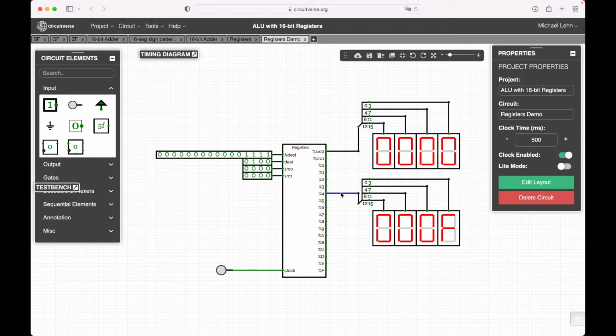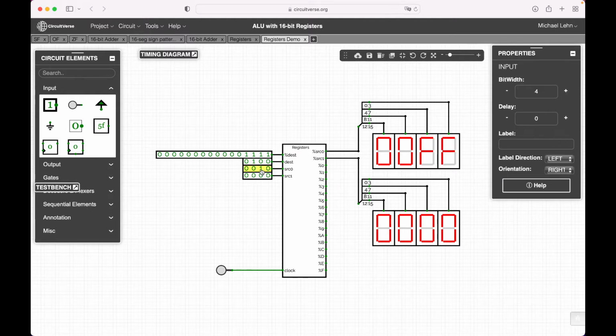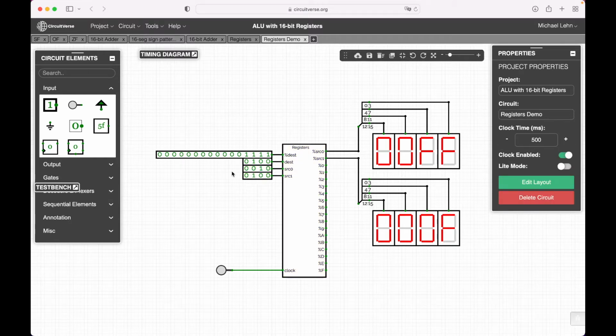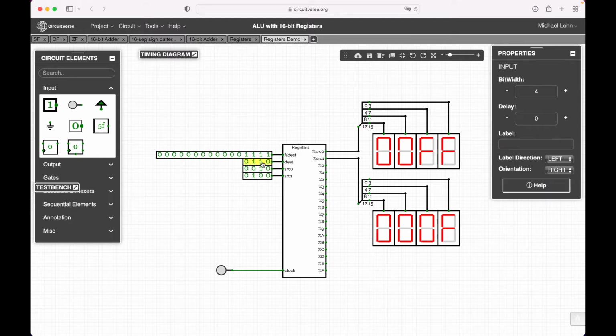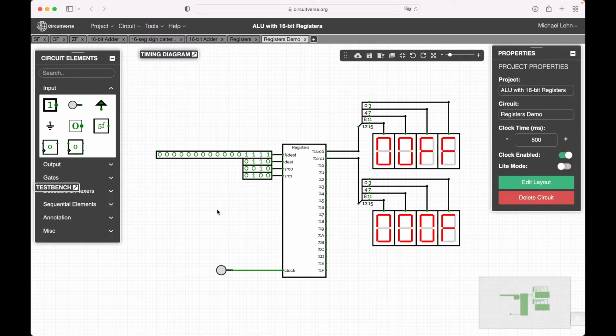So 0 is always the first operand and source 1 the second operand. And then if I want to add register 2 with register 4, then I would use here the ID 2 for the first operand and here the ID 4 for the second operand. And then if I would store the result in register 6, then the destination for the bit pattern computed as the sum of these 2 registers would be the new bit pattern here. And the destination can be selected here.